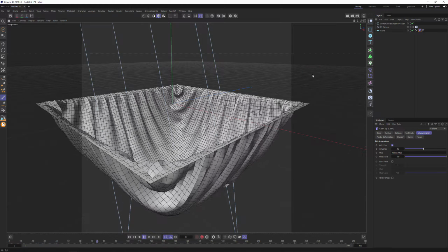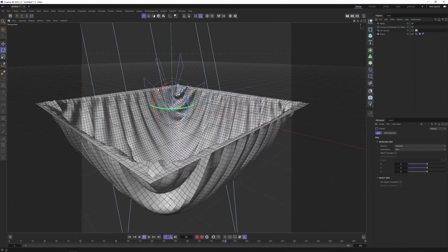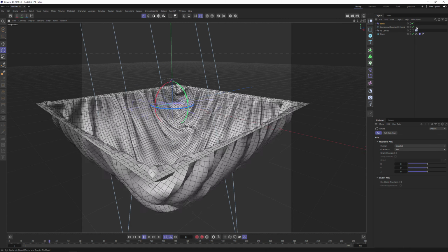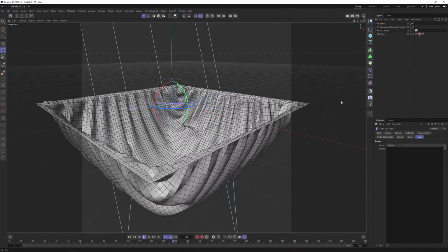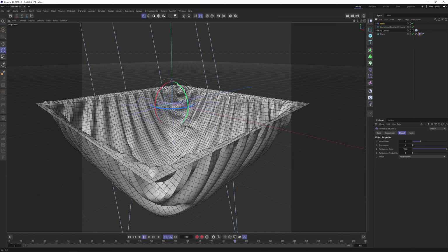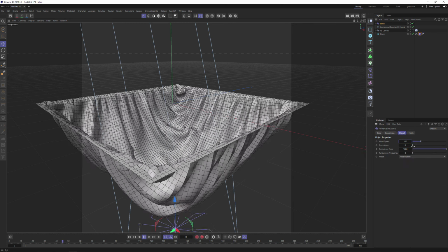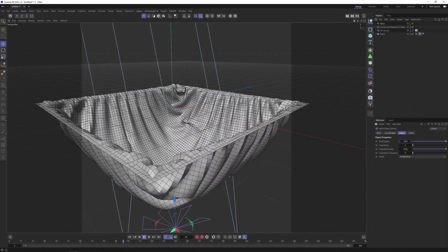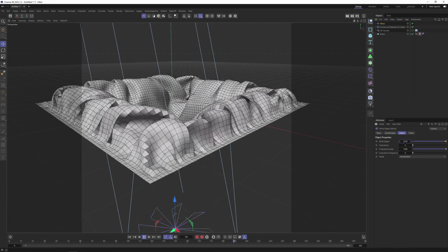Keep it. Also we need some forces, for example a wind force, that will be affecting our cloth engine object. Putting up, going to our tag, and we don't need to bring any forces there, only for exclude. I put wind at the bottom, going to its settings, increase wind speed. We need to find a value that will bring all our simulation up. 2000 seems to be okay.